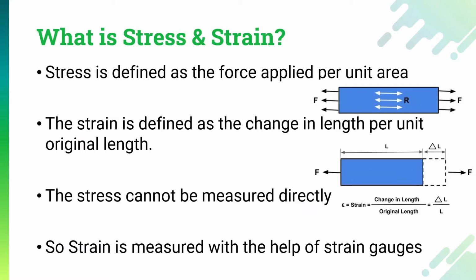Now, stress. Whenever an external force is applied to a rigid body, a resistance force is developed internally, or we can say inside the body, to resist that applied force, and that internal force is known as stress. Mathematically speaking, stress can be defined as force applied per unit area, or we can say the resistive force that is developed per unit area.